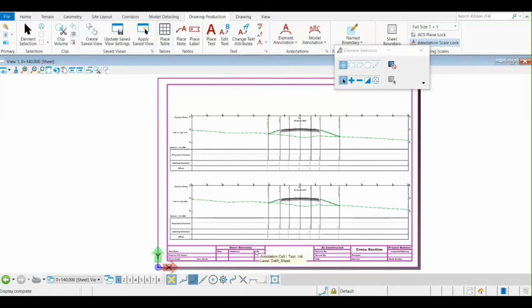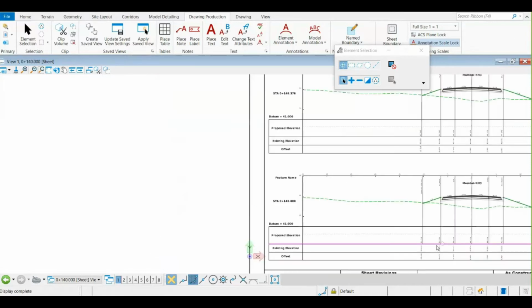So you can create your own drawing sheet within which you can define your own preferences along with the borders or the styling, or even you can change the font size, colors, each and everything can be customized as per your need. So once you create your setting file, a lot of manual effort will be saved, as well as drawing production in terms of your plan, profile as well as construction is going to be generated in a couple of minutes. The earlier, traditional work which used to take 3, 4 days even for a big highway section can now be done within minutes.